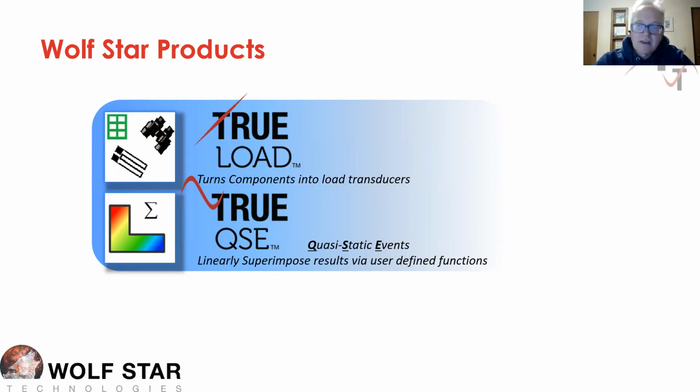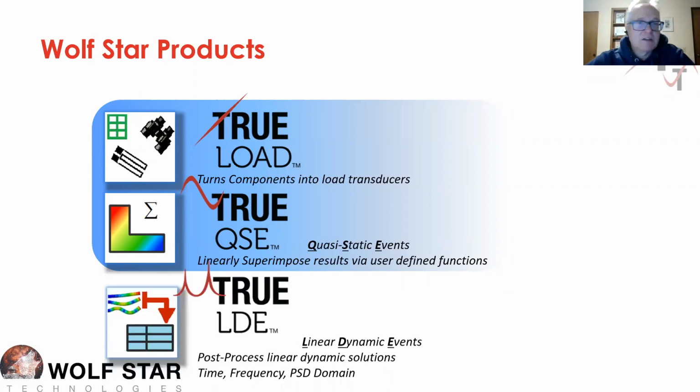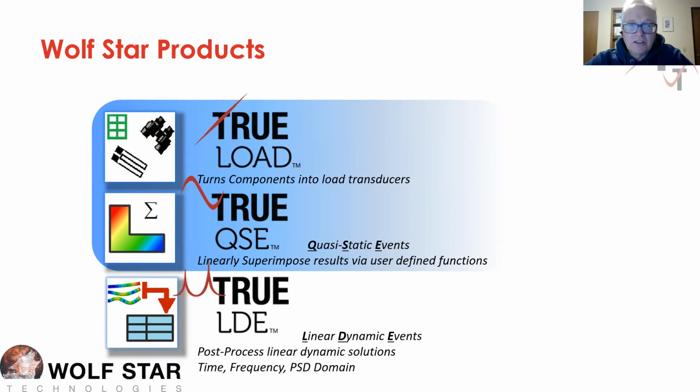Okay. And the third product we've got is a fantastic product we called TrueLDE, and LDE stands for Linear Dynamic Events. And this is a purely analytical tool. It works with your linear dynamic solutions in the time, frequency, and PSD domain, and it's super powerful. It has got lots of capabilities. It allows you to convert your results between time, frequency, and PSD domains. You can query any node or element on your structure for any response you want.